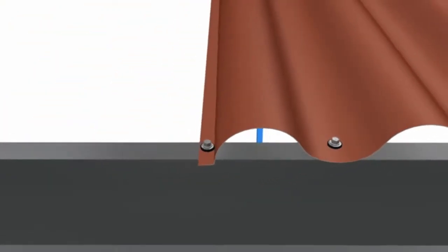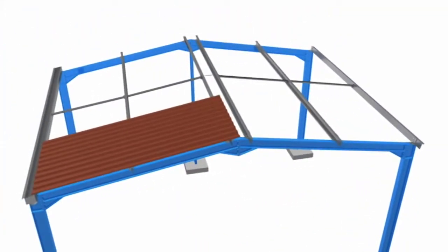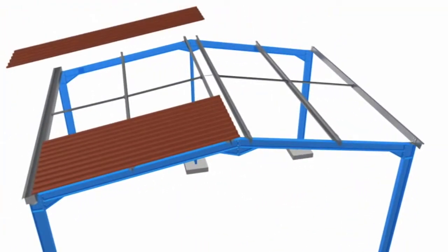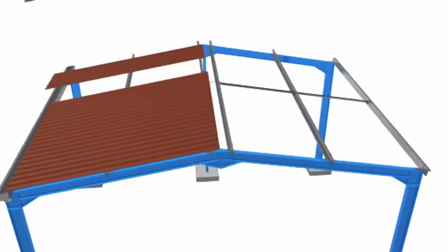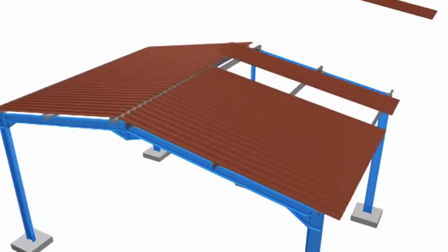The next step was to determine the wind load placed on the structure from the external walls. We obtained the data collected from the bracing design, which allows us to determine the total wind load for pressure and suction. We multiply the load by the span of our shed, a total of 6 metres.